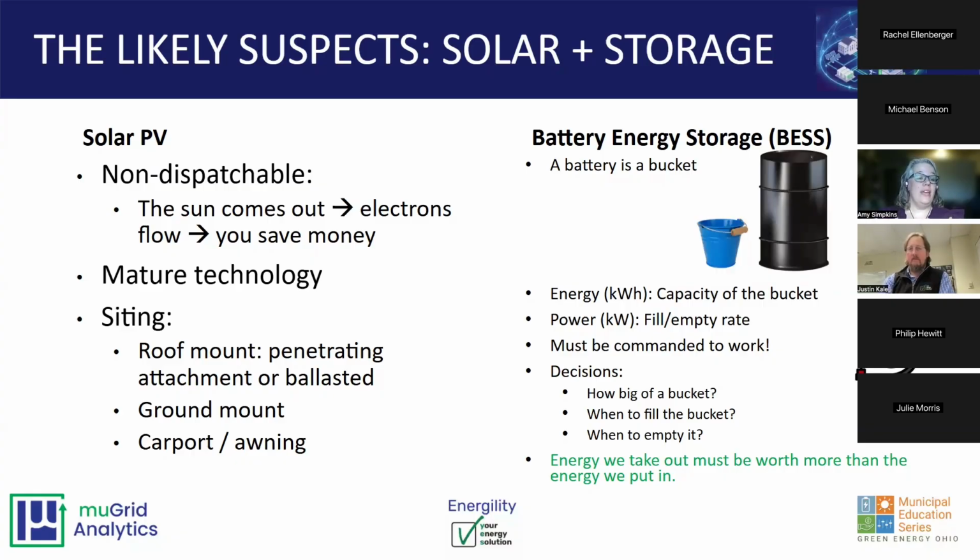And so this is what we look at when we come in. And when I say we, I mean my company, Municipal, I mean Michael as a developer, I mean Justin at Energility. We are going to look at your site and look at what your power needs are. That's your instantaneous rate of consumption, and what your energy needs are. And that's how we work those two things together to pick the appropriately sized battery for you. So those decision points are: how big of a bucket do you need?